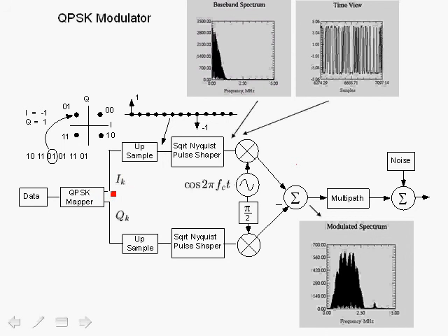However, in actual processing, since we are splitting the symbol into its 2 components, each chain represents the processing of a real number. Just as in the case of the binary baseband digital communication link we had before, we take the symbol, upsample it, and generate impulses, where each impulse represents the symbol, and that is input to a square root Nyquist pulse shaper, whose output is a superposition of the impulse responses corresponding to each symbol.